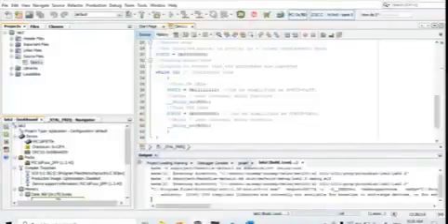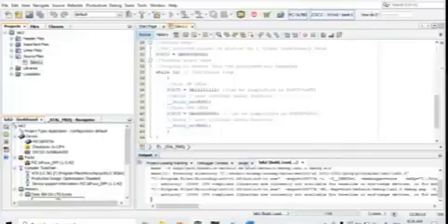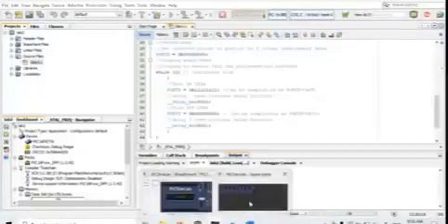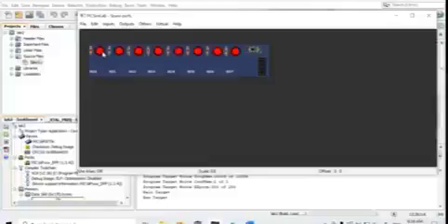If your window does not contain PICSIM, wait till the tab appears. Okay, PICSIM will be available. So you can see run target. So this is the blinking, on 500 milliseconds, off 500 milliseconds. So that one concludes exercise 1.